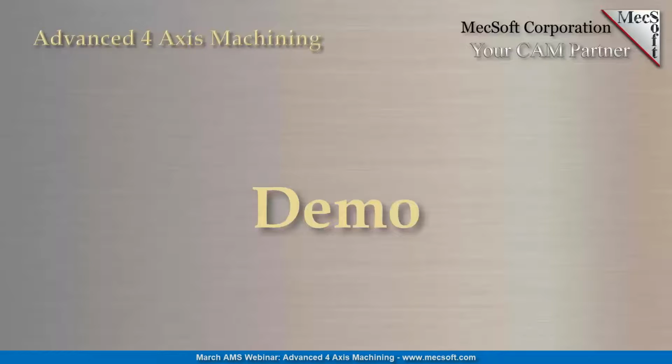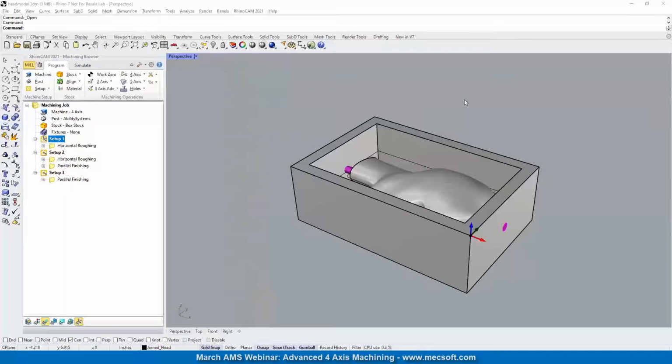First, I will be starting out with the index 4-axis machining, also known as 3+1 machining. We'll cover this in one of our CAM products. We'll be focusing today primarily on the RhinoCAM suite of products, and the workflow would be very similar in all our other CAM products. Now, the 4-axis module is available starting with our Expert configuration. So if you have Expert, Pro, or Premium, you will have access to these 4-axis machining methods. You can do both indexed machining in 4-axis as well as continuous machining.